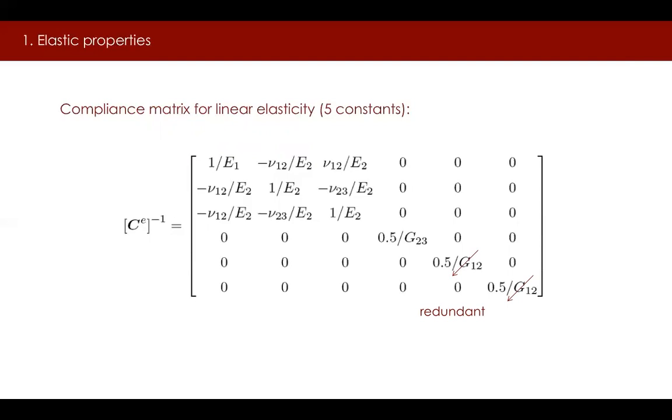In the isotropic case, we know that the Poisson's ratio is required to have a value within the interval -1 and 0.5 for the material to be stable. However, for a transversely isotropic material, the Poisson's ratios have no bounds. That is to say, they can be less than -1 or greater than 0.5.